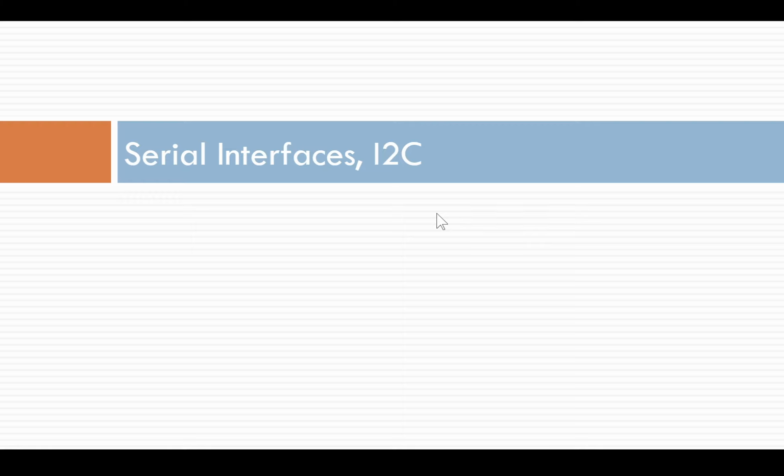Why? This is actually why. I2C stands for inter-integrated circuits, so between integrated circuits bus. It's relatively slow speed, but it's an addressed line. So the slave devices have an address.